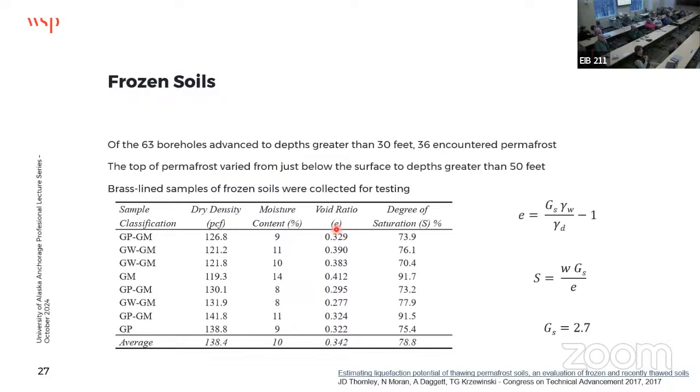So that's a great comment, and this was kind of hidden in the weeds, if you will, of some of my commentary. I had that N160 clean sand, and that CS, and they've accounted essentially for fines content there, up to roughly about 35%. Now, this gets into the shift from classical liquefaction. If you queried most geotechnical engineers, they'd say you need to have sand to have liquefaction, right?